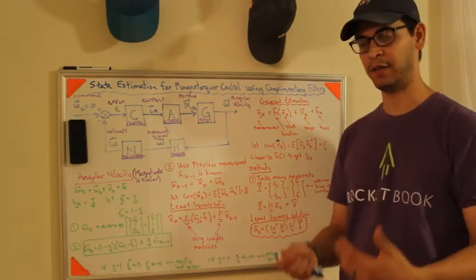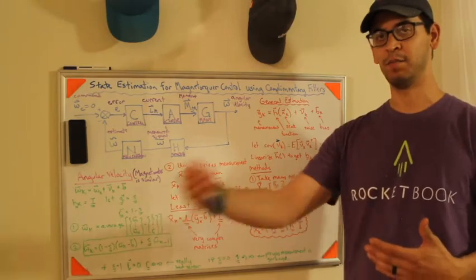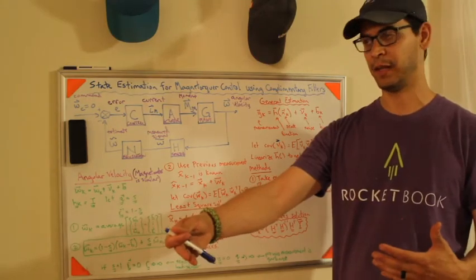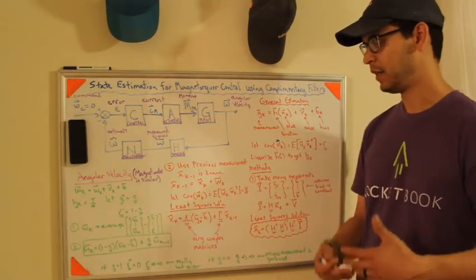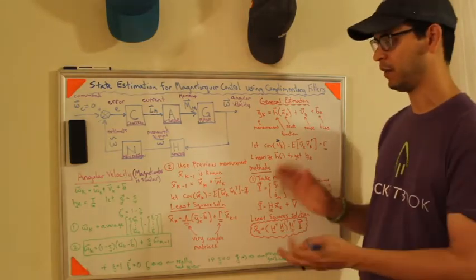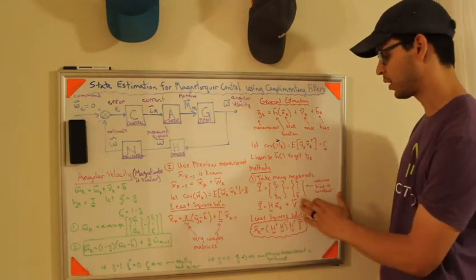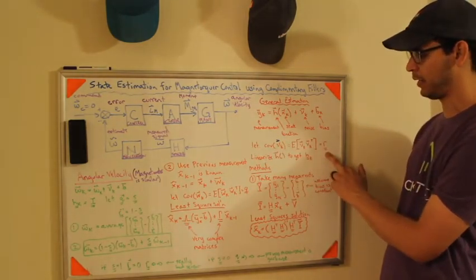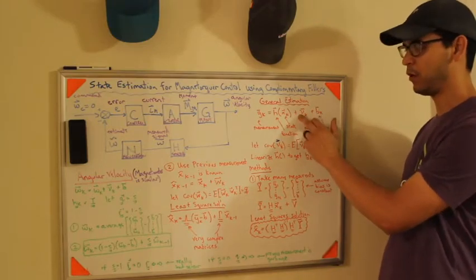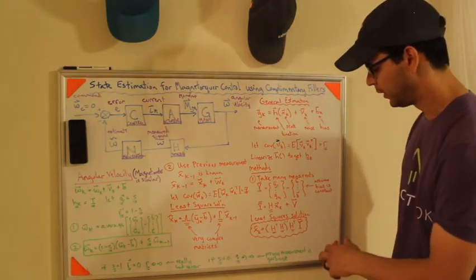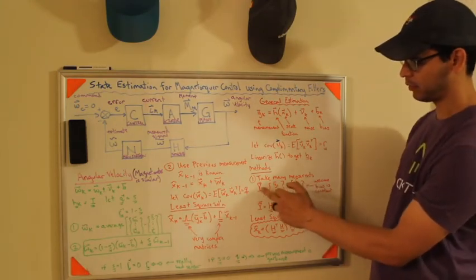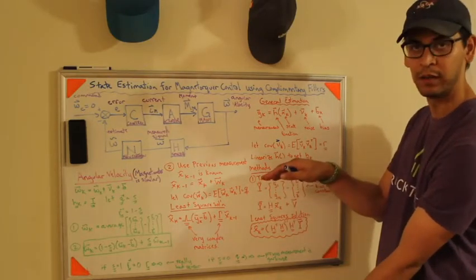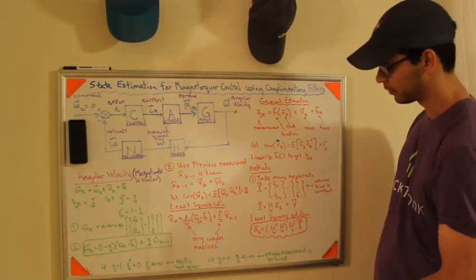Getting the bias is very hard, and there are more complex filters out there that will estimate the bias for you, like an extended Kalman filter, an EKF, if you want to Google that and take a look at it. For this seminar series and this example, I'm not going to go into that, and I'm just going to assume that you do know the bias. You don't know what the noise is, you have an estimate of the covariance, but you don't know the noise, and you're trying to filter that out. So you subtract off the bias from every single one of these terms and put this into a big matrix called y bar. So this is a huge matrix y bar, an n by 1 vector.